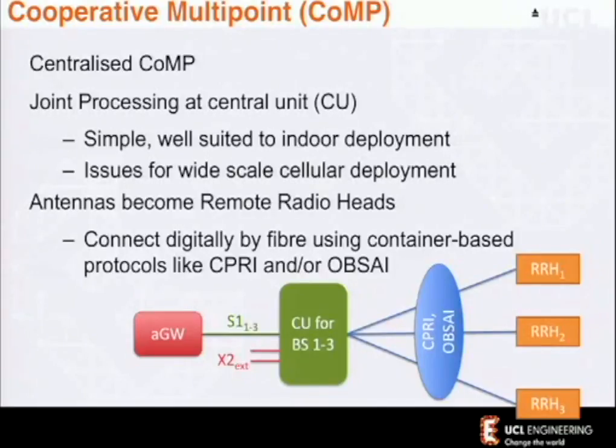We know that the maths of that is well known. What is more challenging is, well, yeah, that's cool, but MIMO is relatively easy when my two antennas are sitting next to each other and I digitize and I can do all the processing on an FPGA or an ASIC that sits all in one place. What happens if I know something here and I know something there? How do I co-process that? How do I work out that I know this, I know that? When it's waveform data, it's waveform level with two separate channels that I'm trying to co-process. That's not so simple.